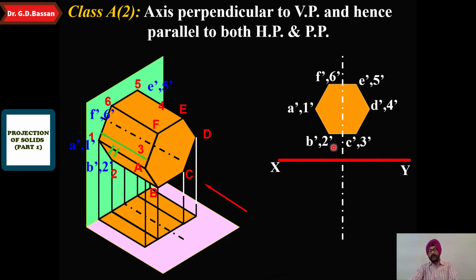Okay, now as we draw the front view first, then from the front view we take the projections, and we are getting the top view at the horizontal plane. So while taking the top view from the top, this is H, which is the axis length that has been given. Now A will be projected here, and that would be shown from here. 1 is projected on the other side. So 1 dash is here, and that will be projected here, that will be 1. In the same way we have to project all the points on the horizontal plane.